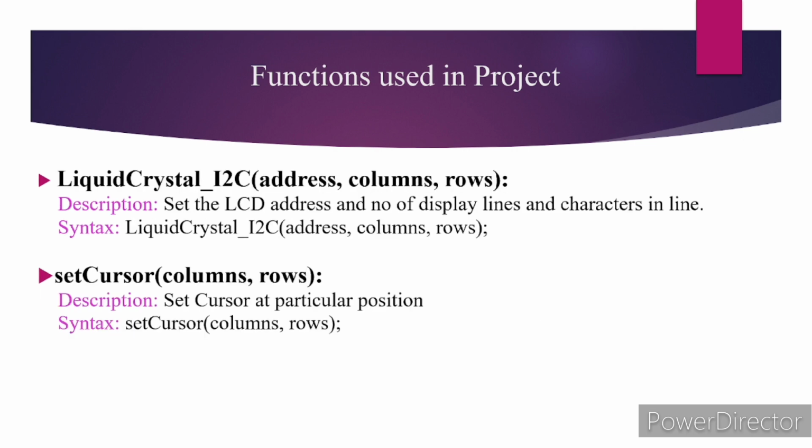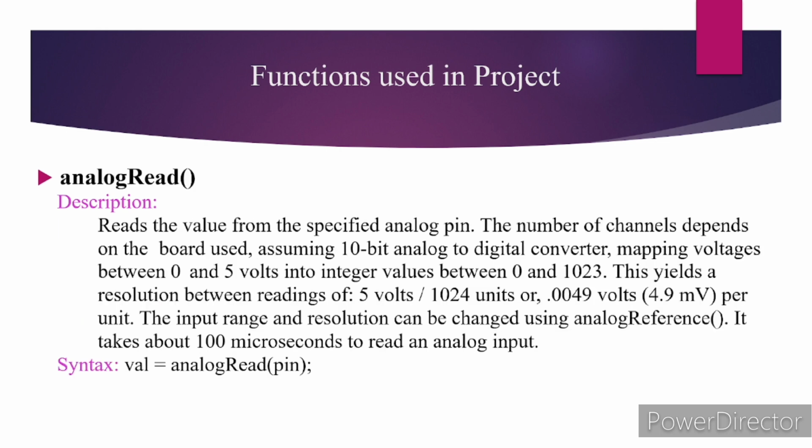The functions used on CLCD are LiquidCrystal I2C and setCursor. The LiquidCrystal I2C function sets the LCD address and the number of display lines and characters in a line. setCursor takes columns and rows. It sets the cursor at a particular position.